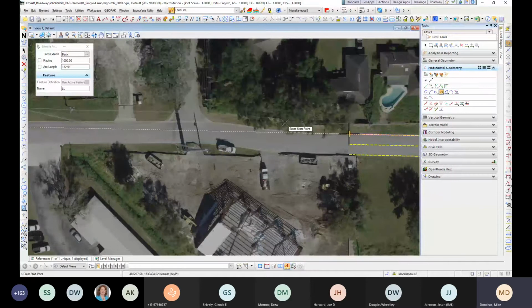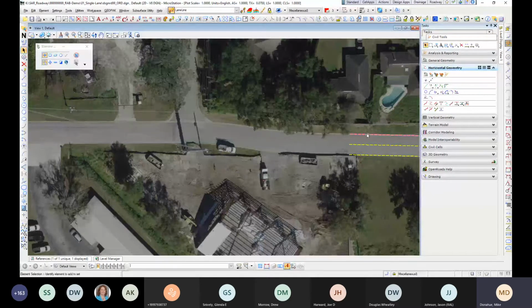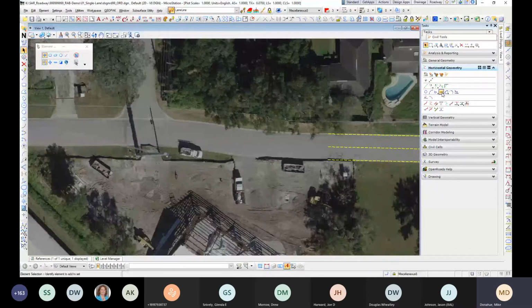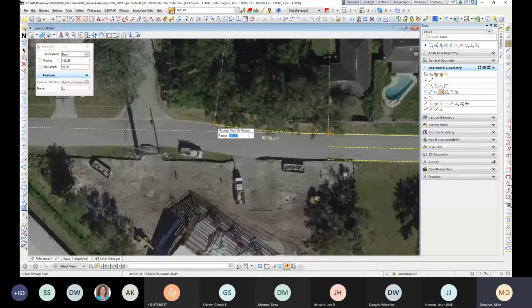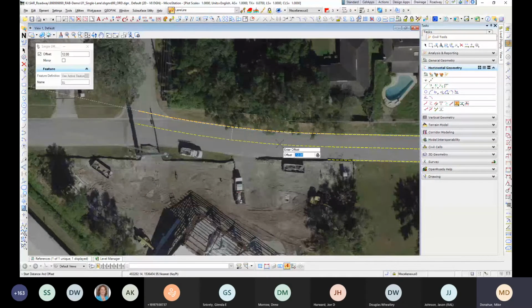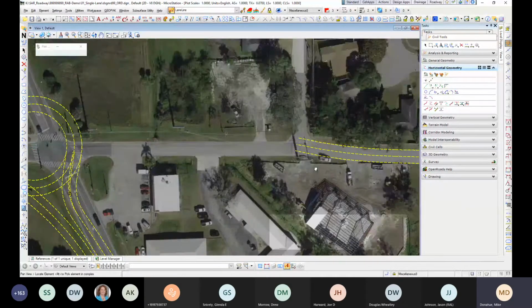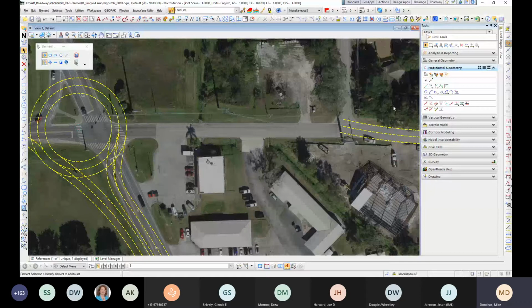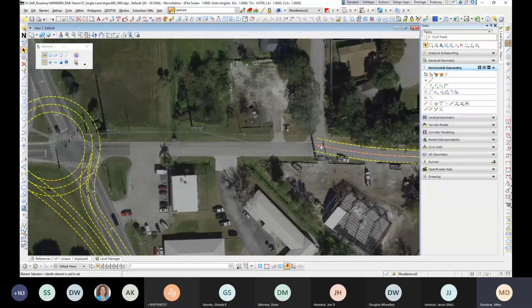And I'll draw these. That's not quite where I want it. I'll draw these again just to try and mimic the existing so I can establish the geometry I'm looking for. I'll offset this as well. I know I want, again, a certain length of tangent here. And now I'm going to switch over from drawing on the outside. I'm going to use this offset element on the inside.